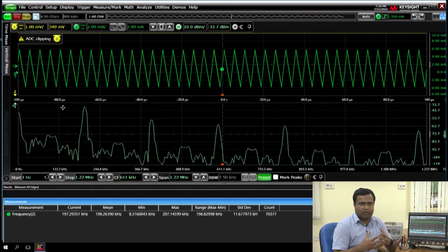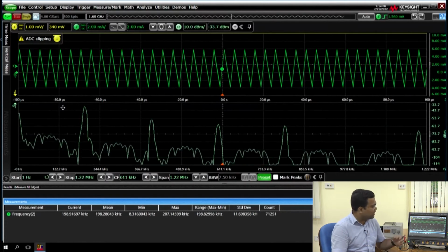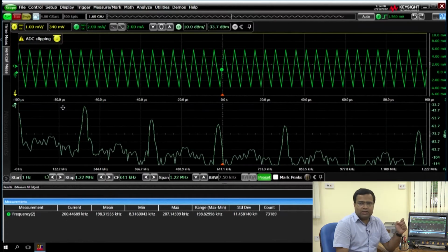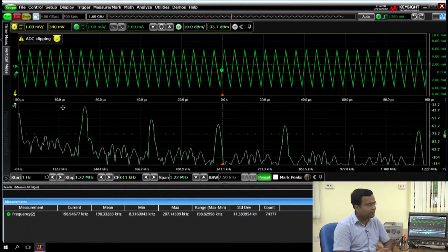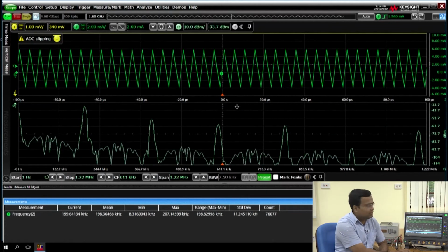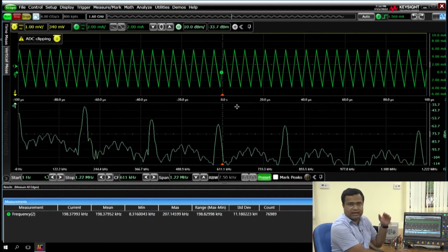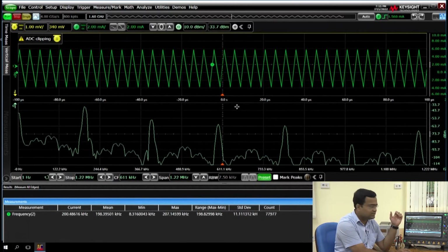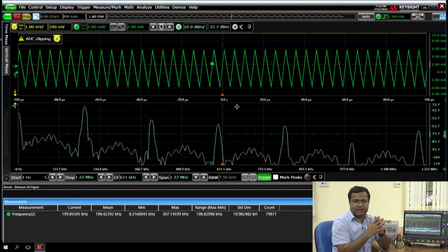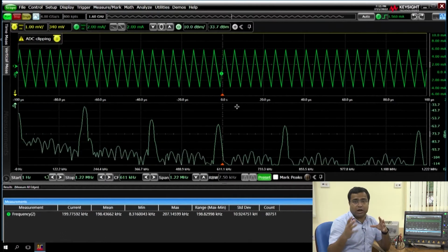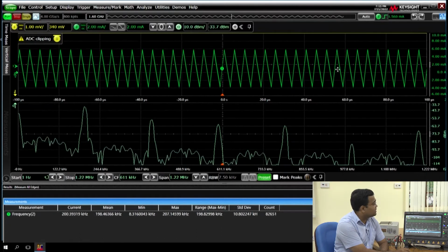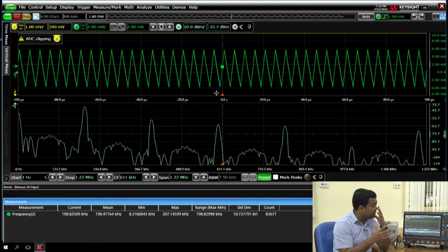Okay, I think Nitin has already demonstrated how to get the power spectral density of the switching signal. Here I want to add some more information. Here you can see the inductor current of this buck converter, and we are running using the inner closed loop. That means it is a current mode control where only the inner loop is closed, and it is a mixed signal current mode control. We have not closed the outer loop. In this condition, the converter is running under stable periodic behavior.